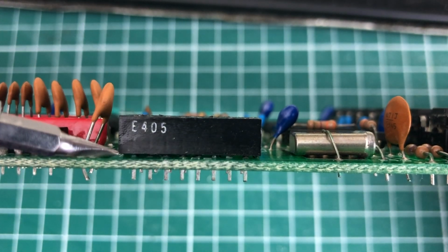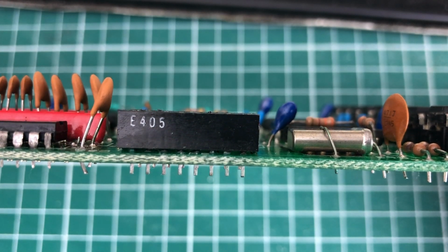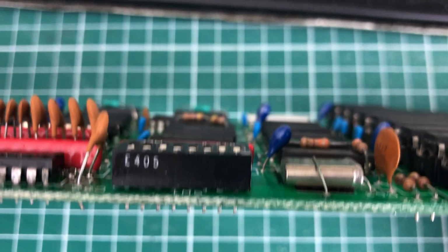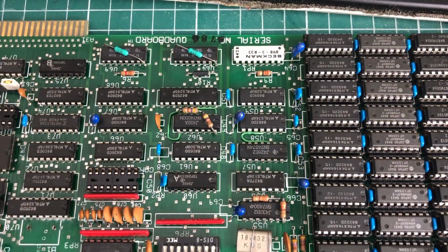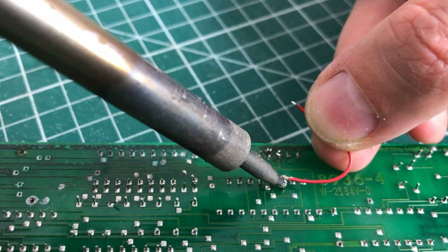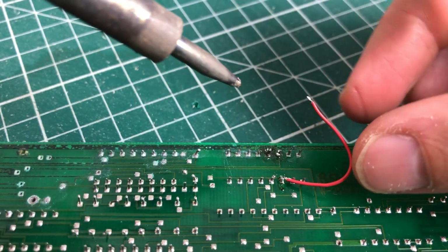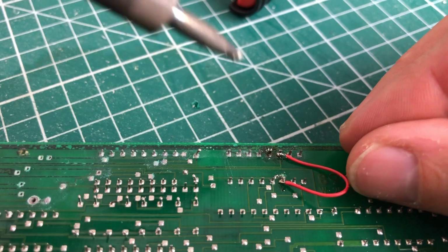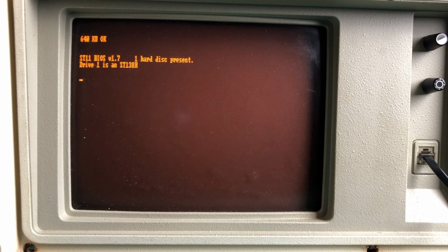Now I don't have a spare switch block now, and I want to move this project ahead. So what I'm going to be doing is short-circuiting the switch to enable the memory directly using a piece of wire, so that the additional memory will be enabled and we can verify if the machine will actually detect the additional memory. So as it's counting upwards, it reaches the critical point of 256 kilobytes, and it does in fact continue counting all the way up to 640K, which is very nice.